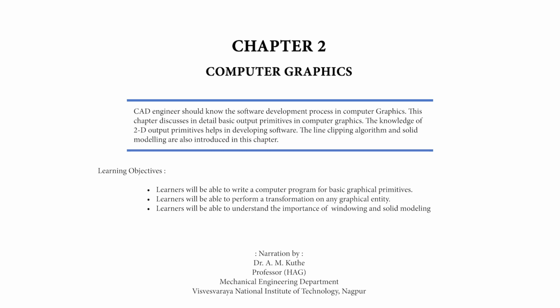CAD systems provide extensive surface menus from which surface modeling can be easily done. These include plane surfaces, tabulated cylinders, ruled surfaces, surfaces of revolution and sweep, fillet and sculptured surfaces such as Bezier, B-spline patches, etc. Refer figure 2.28.